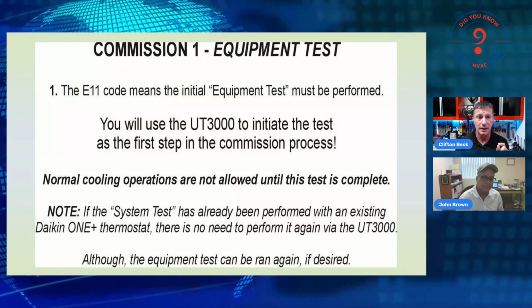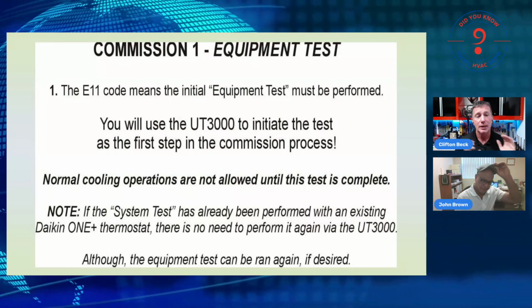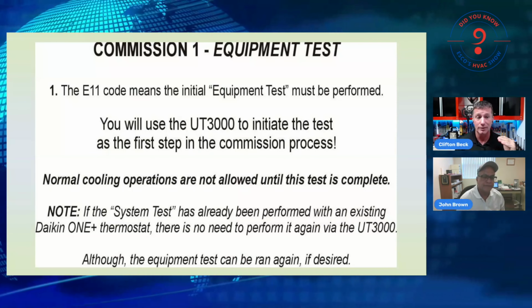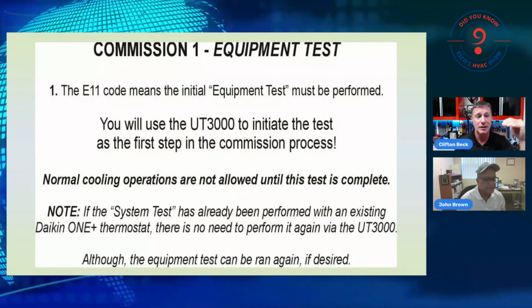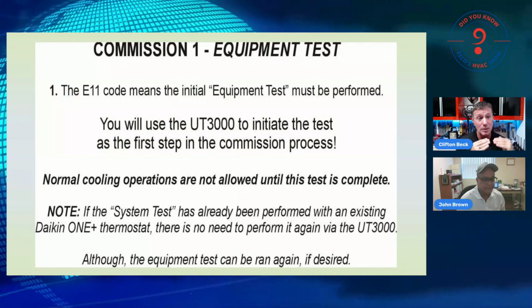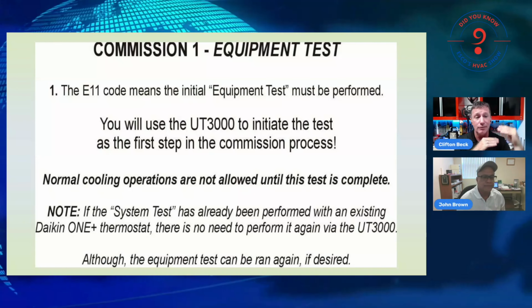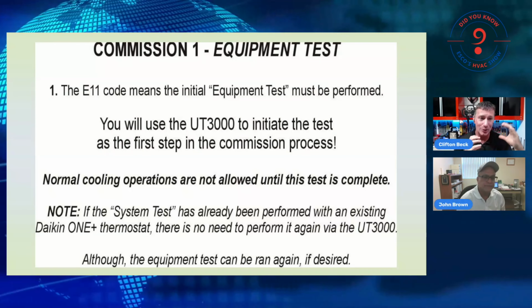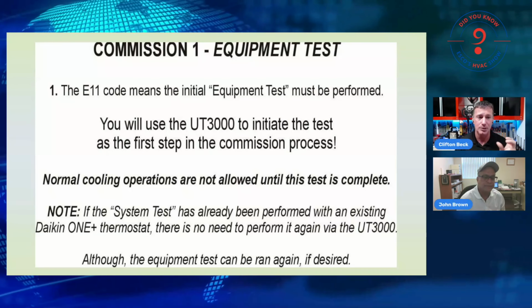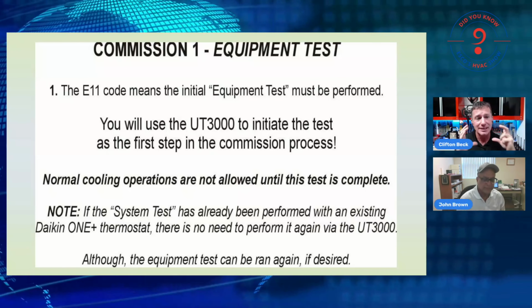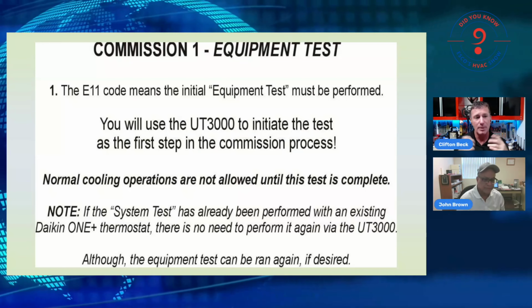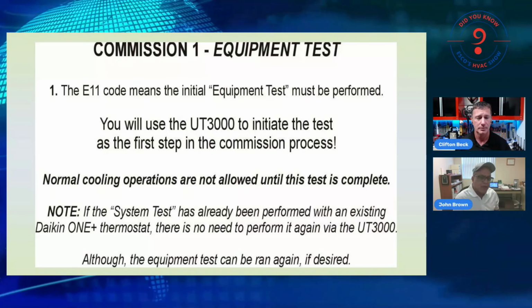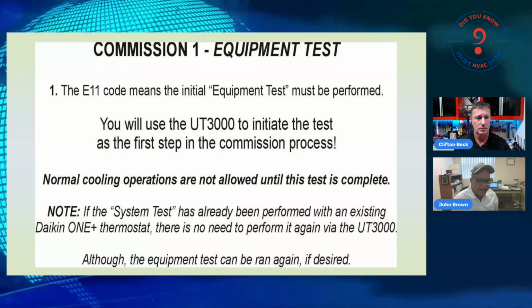If they're doing a system verification test, and this is any manufacturer, we may not start a compressor right off the bat. We may start a condenser fan motor if it's an ECM so we can vary the speed of it and check amp draws. Then we might turn on a compressor and ramp it around a little bit, looking for different parameters of amp draw. Then we might turn on some airflow and open expansion valves. So we're reading temperatures and pressures to see that the system is compatible and that our capacities are matching properly. So it takes a little while, 7 or 8 minutes on a lot of these. On average, it takes about 8 minutes or so.